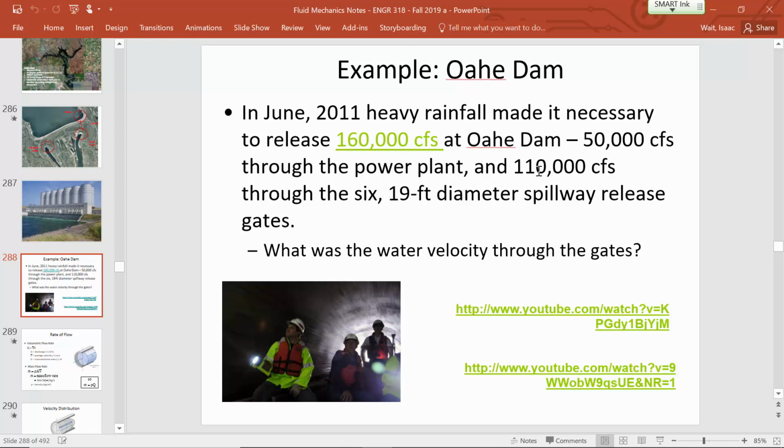you can guarantee that concrete has been finished with a lot of care and attention to how smooth it is. It's likely been reinforced with much more steel than would typically be used for ordinary curb and gutter work. So it's a specialized environment. In fact, in some dams where they have water flowing through penstocks at a really high velocity, they'll actually inject air so that the water rides on a cushion of air instead of coming in direct contact with the concrete, just to prevent scour and cavitation and damage to the concrete.